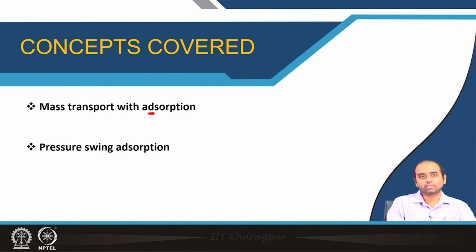Now, what is pressure swing adsorption? Pressure swing adsorption is generally followed for gas separation, because the adsorption bed becomes fully saturated quickly. So you need a swing in the pressure: if you depressurize it, the adsorption bed becomes regenerated once again. By altering the pressure cycles, which is what is known as the pressure swing process, you can have a cyclic process of regeneration and adsorption.